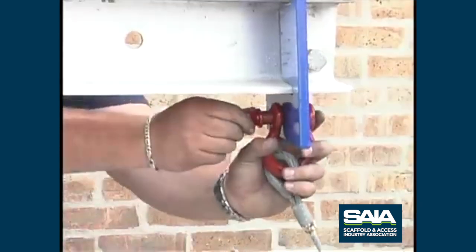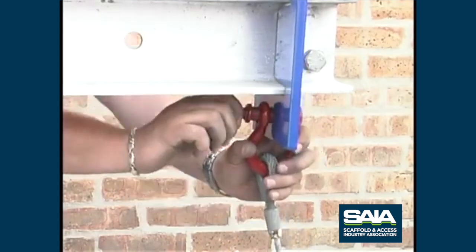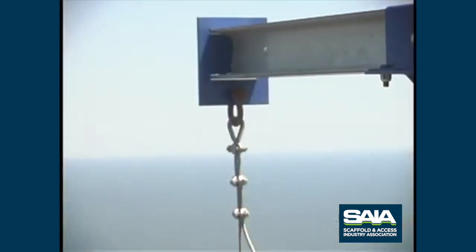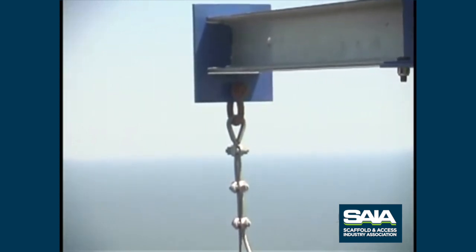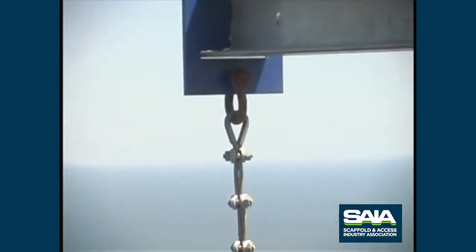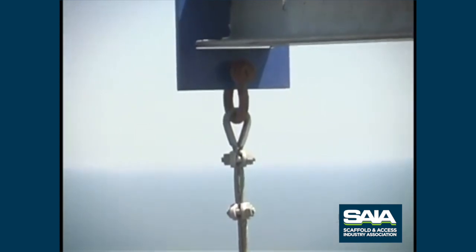Secure the upper end of the wire rope to the suspension point. There are several methods of doing this. If you use wire rope fittings, you can protect the wire rope from damage and make a stronger connection by using a thimble, 3 J-type wire rope clamps and a shackle.